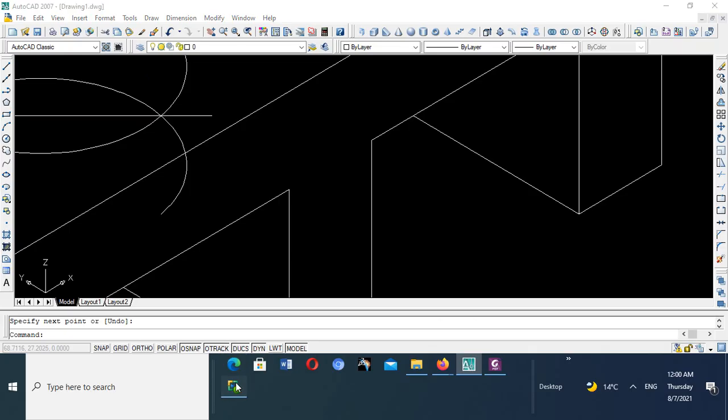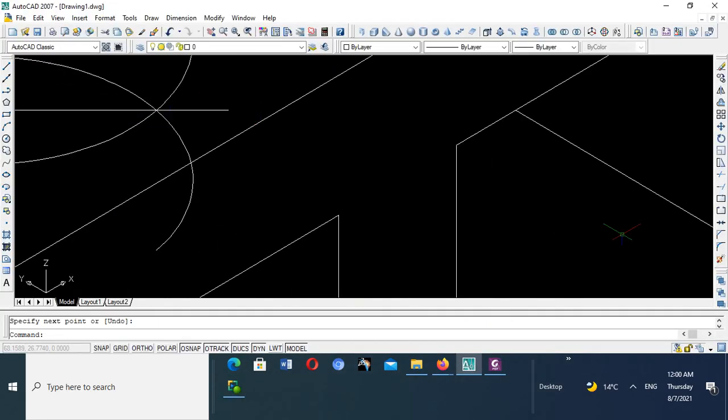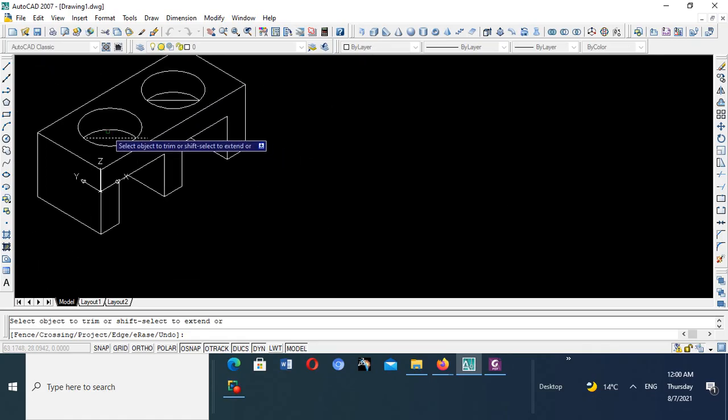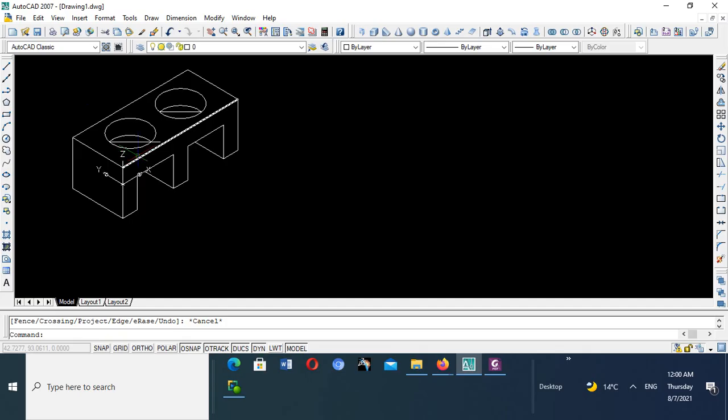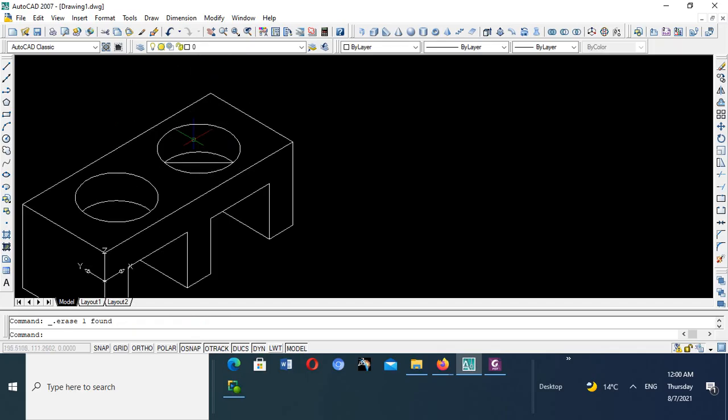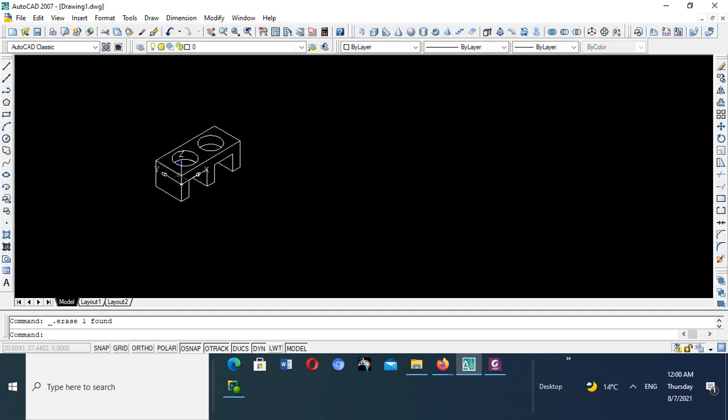So we go again for trimming, the last command. We pick trim, then this is our trimming edge. We press enter, go ahead, trim. This one was the stubborn one. You can try and click now, and now it is gone. Now we don't want this, so we delete it straight away. We're just using them for trimming. We don't want this again, delete it, and then check.